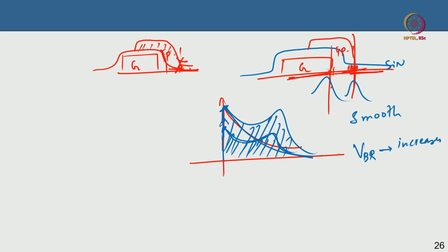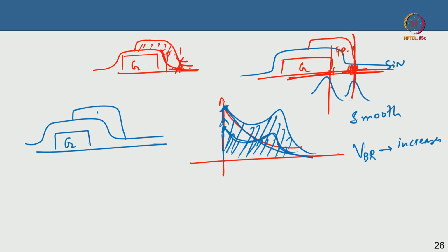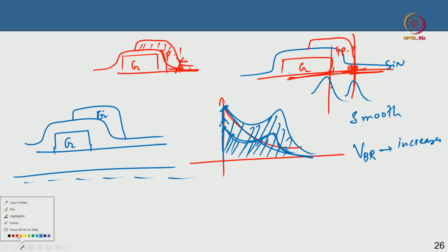In a more qualitative aspect, you can say that there is a gate here, okay, there is a dielectric here, there is another gate here for a gate-connected field plate. You can say there is another gate, it is only metallically shorted. And this is your 2DEG, okay. So suppose this is some thickness d, and the silicon nitride here could be 100 nanometer, or depends.